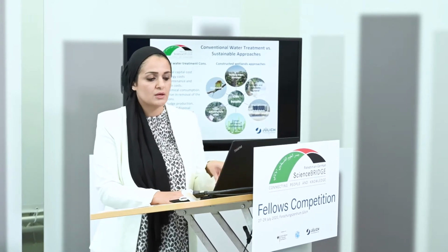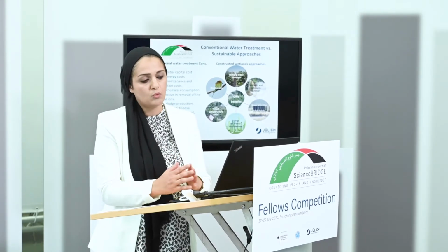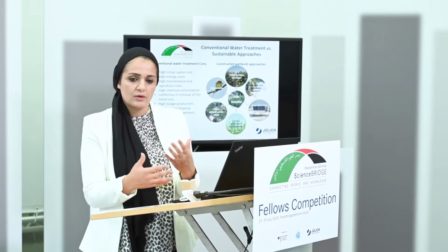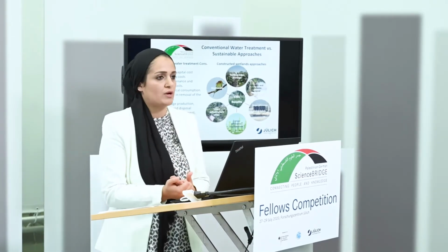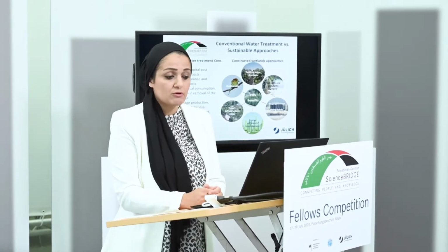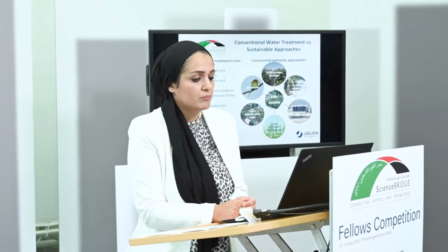Also, we can retrieve nutrients from constructed wetlands after the water with nutrient pollutants came in contact with the media. We can use this media as a fertilizer for agriculture. Of course, we can use the sludge for biogas generation. Also, the constructed wetlands have, as I said, zero energy consumption, so the energy efficiency is improved.